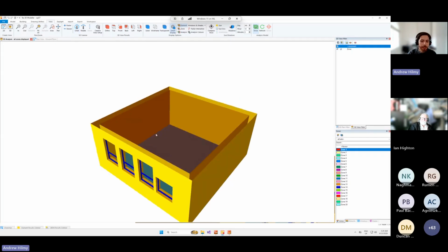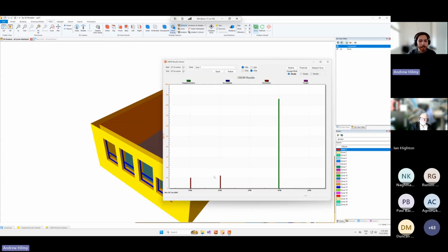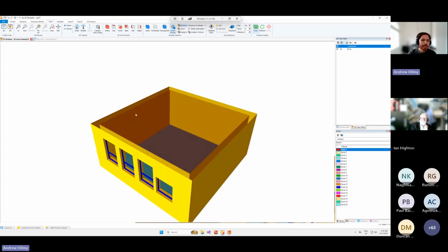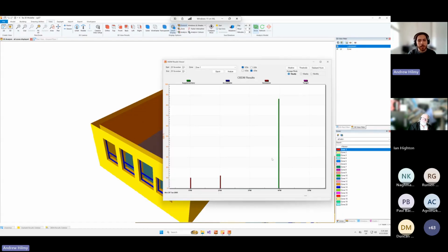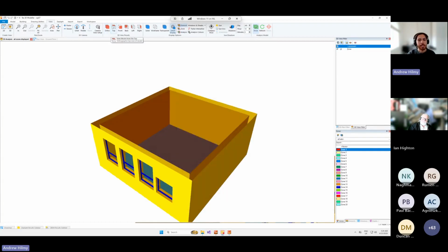When you do that, in the past I've identified periods where we're getting an unexpected amount of direct sunlight where it's excessively bright, rendered a view, and then seen the sun patches and how they're coming into the space. Then you could put an external shade outside the building or a light shelf to reduce those hours where you're getting too much light, or for the hours where it's a bit too dark, try to increase the amount of light at the back of the space.